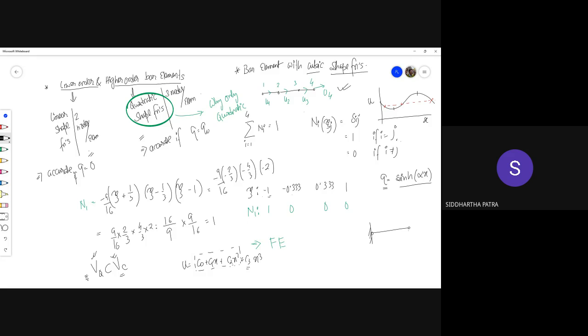But that's not the point. Getting the accurate solution has never been the point, because it's a numerical method. We just showed, as an observation, that with no distributed load the linear shape function gives you an accurate result, and with uniform distributed load the quadratic shape function gives you an accurate result.